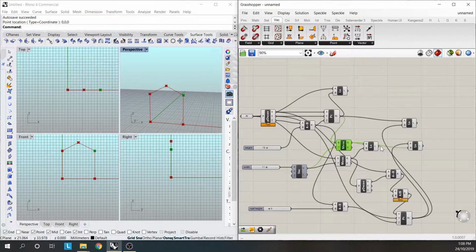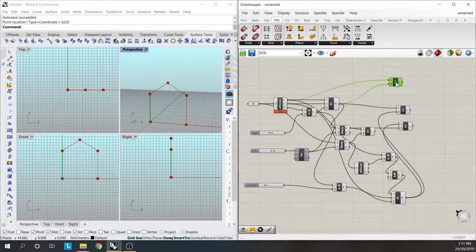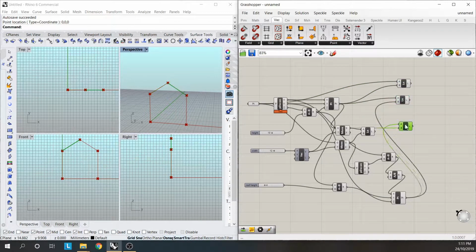It pays to do these in the right order because it's going to help later when we start manipulating the lines. There are shortcuts you can take, but it's best to do it this way sometimes. Now we've got all our points of the portal frame. I'm just going to rearrange them slightly so that we've got first line, second line, third line, fourth line.